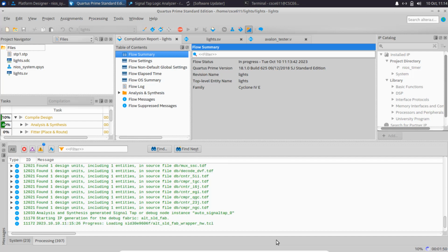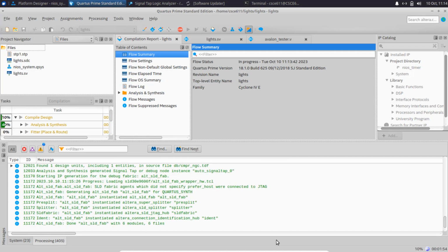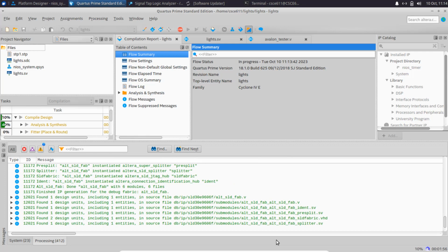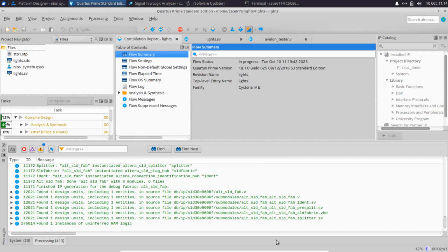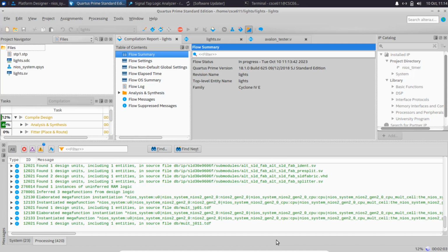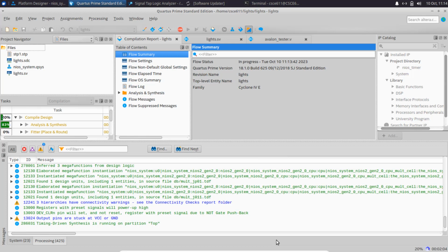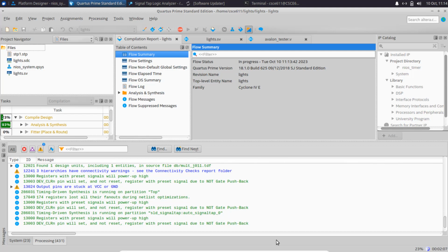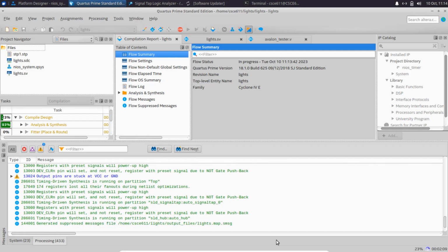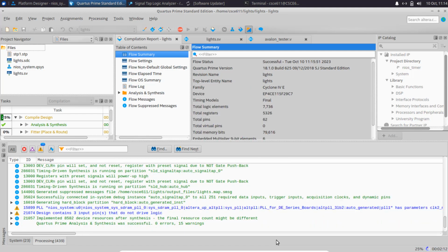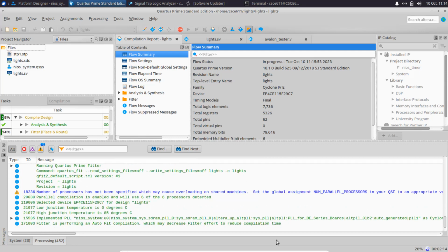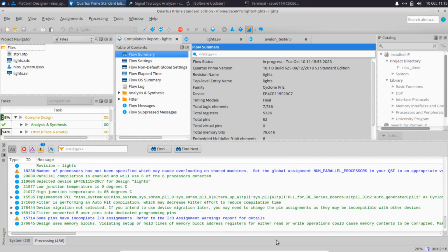So once this gets done, in SignalTap, you have to set a trigger condition. So you can tell it what moment in time you want it to show the signals that it captured. So I'm going to trigger on the rising edge of read, right? Because remember, I used the one that was active high. So read's going to be low, and when I read from the peripheral, it's going to go high. Make sense? I could also look at chip select, or I could look at write if I'm looking for a write.